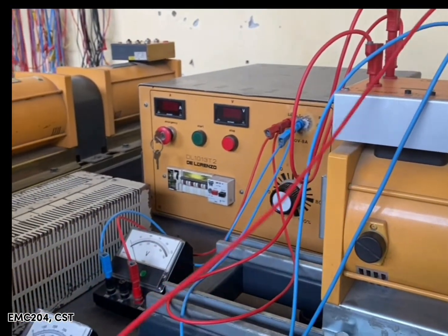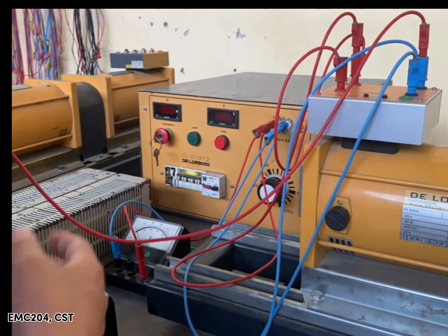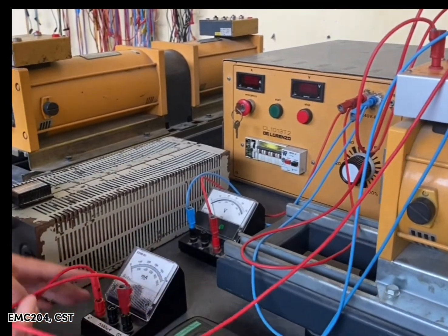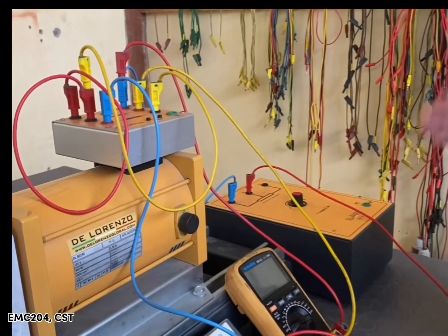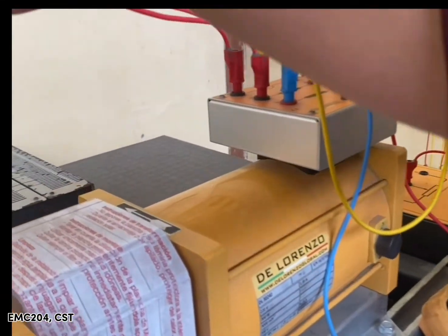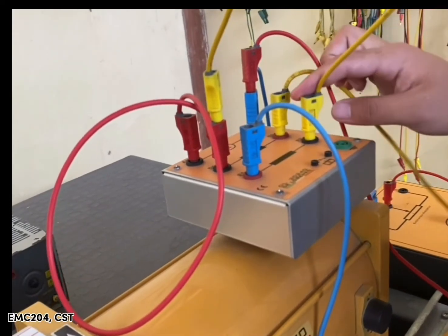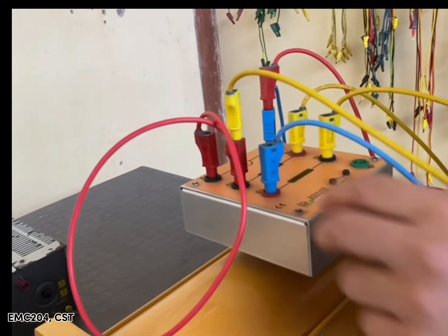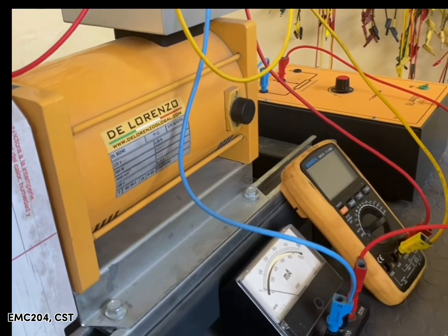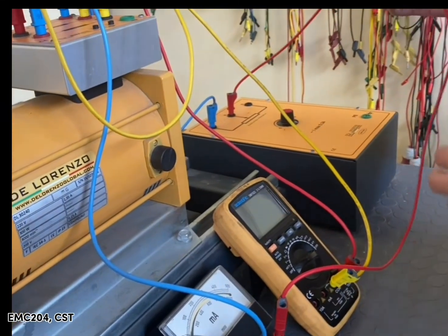Now to measure the field current and to maintain it at constant or rated current, we have to connect an ammeter as well as a voltmeter. In case of generator side, we have to short circuit the A1 and D1, whereas D1 is connected to the E1. Then from the E1 we are connecting the ammeter to measure the field current, and from the ammeter it is connected with the rheostat.